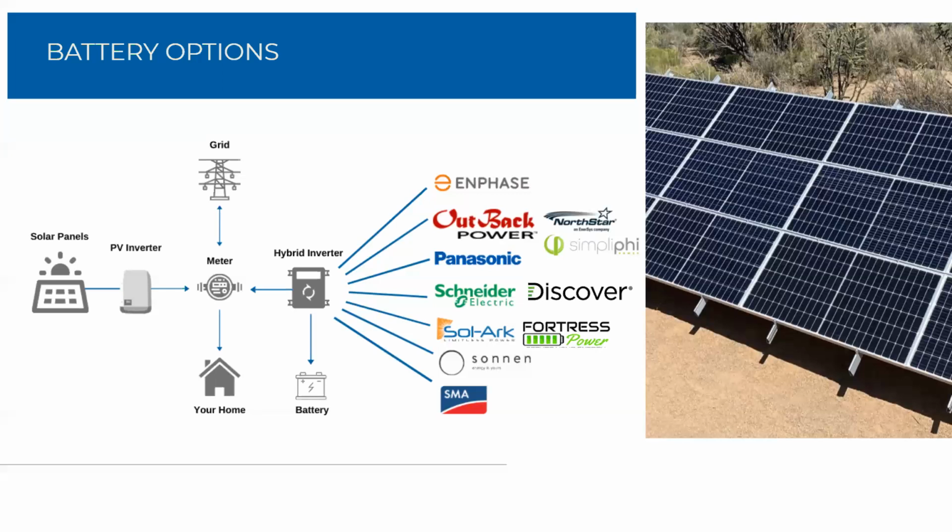Most people are going to draw more than that, or they want a few kilowatt hours for a few days. So even if we look at my lowest example of my house for 4 kilowatt hours, I wouldn't even want a 4 kilowatt hour solution, because I'd rather just get a 10 kilowatt hour solution and know that will last me 2.5 days.